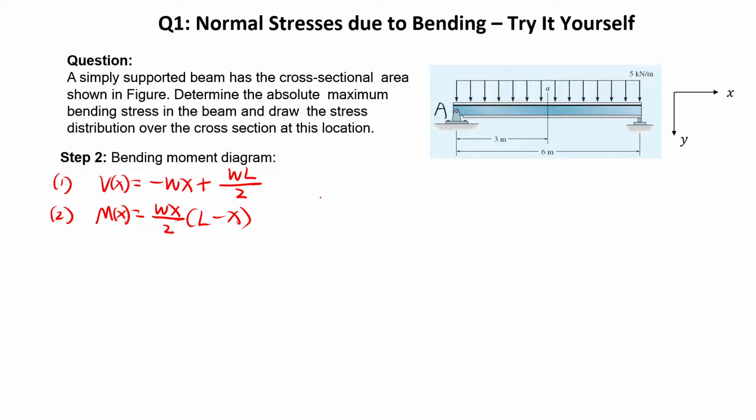Yes, effectively this should be enough, because along the beam, the stress you cut on the left hand side will be no different from cutting on the right hand side. So using these two equations, you'll be able to draw the force and moment diagram.